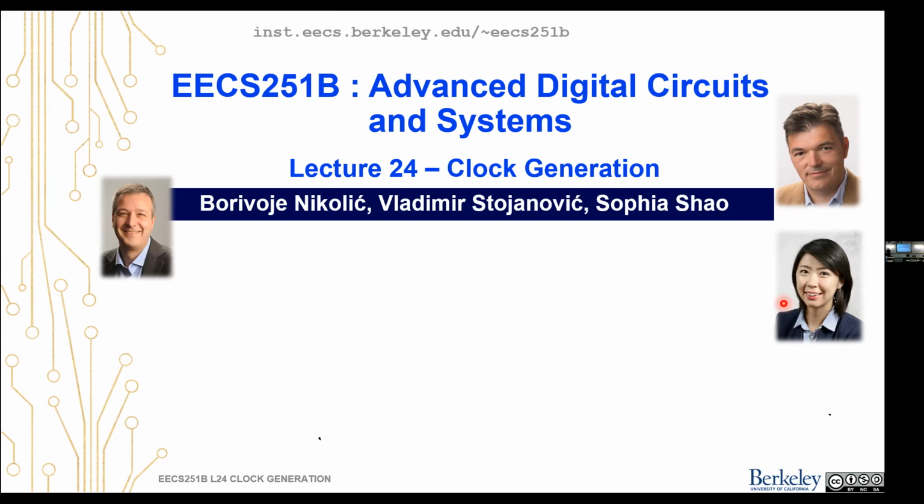So we're building big digital chips, but there has to be a source of clock on that chip somewhere. And especially as the ASICs and the big SoCs are working in multi-gigahertz frequencies, you need to bring in a lower frequency reference clock that usually comes from, let's say, a crystal on the board.